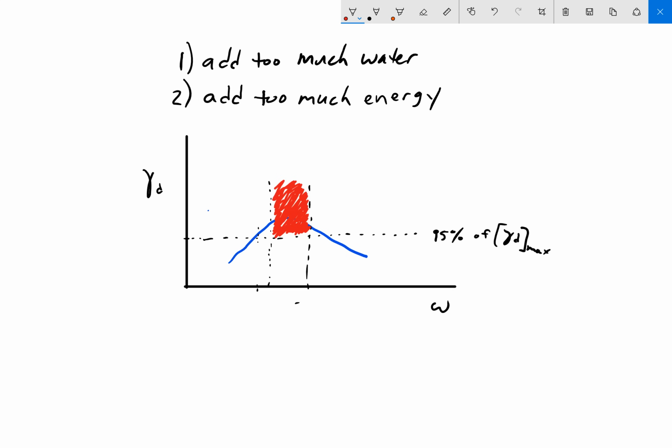If the contractor meets the dry density specification but is too wet, it's bad. If the contractor meets this density specification but is too dry, then that's bad. If the moisture content specification is met but the dry density is not met, it's bad. And so in all of those cases, the soil would have to be ripped out and the contractor would have to redo it.